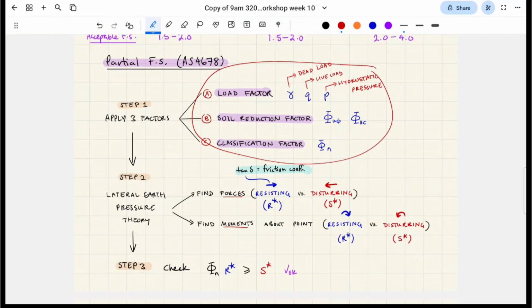So when you're designing the capacity of that scaffolding, are you going to design it to hold exactly 300 kilos? No, probably not, right? What you'd probably do is exaggerate the loading in your calculations, and for the capacity of the scaffolding, you'd reduce that by some sort of factor. That's just how it works in Australian structural design. So we're doing a very similar thing. We're going to apply that concept to geotech design, because it works a little bit different.